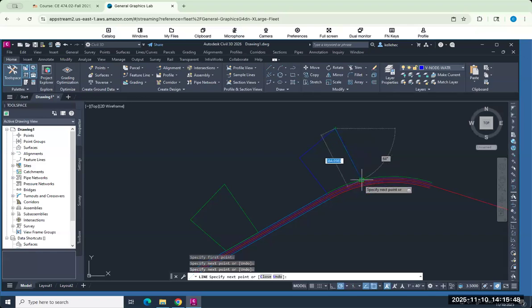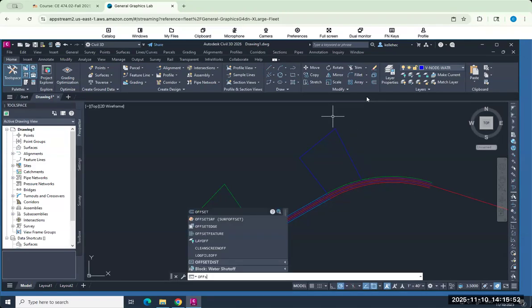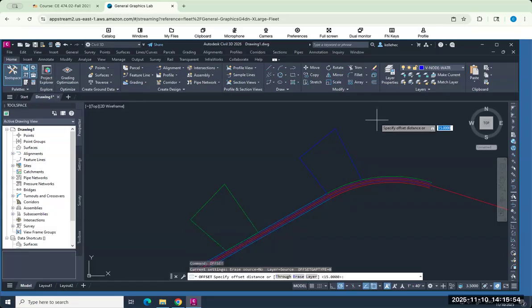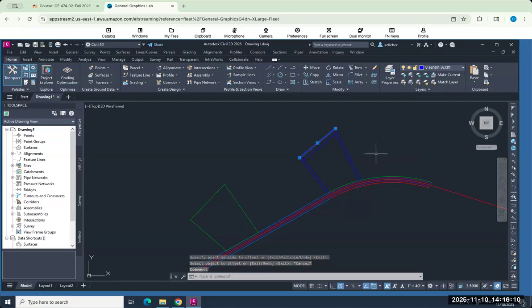So I have lines here, and all I'm going to do is say offset. I want to keep it at 15 from the sides. So I'm going to offset inward, and let's say it's 30 from the back. I'm going to say offset 30. Okay, I'm on my offset layer. Now I'm just going to delete those lines that I drew, right?